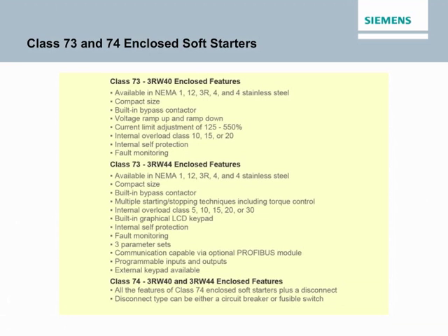These non-combination styles come standard with a choice of NEMA 1, 3R, 4, or 12 enclosure, a control transformer, soft starter with built-in overload and bypass, line side power terminal block, and a reset push button. A wide variety of factory-installed options are also available.